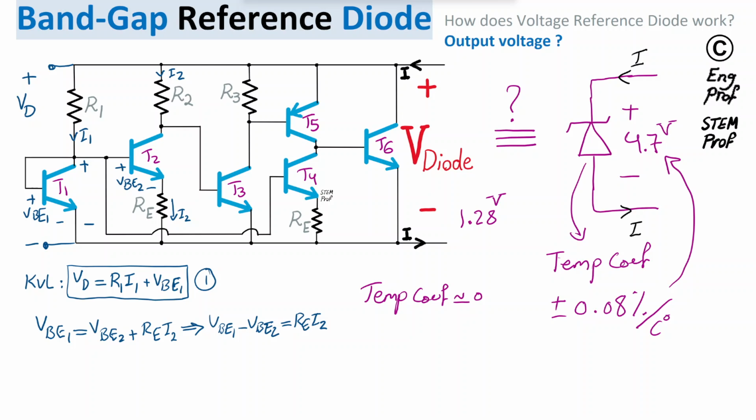What I'm going to use now is the famous Shockley PN junction equation, which is the equation that governs the IV or current-voltage relationship for the PN junction of a bipolar transistor, which says the voltage of base emitter is equal to the thermal voltage of the junction, which is roughly, at nominal temperature, 26 millivolt, times natural log of the emitter or collector current. It doesn't matter which one we refer to, approximately divided by the saturation current of the transistor. So this is the well-known Shockley PN junction equation for bipolar transistor.